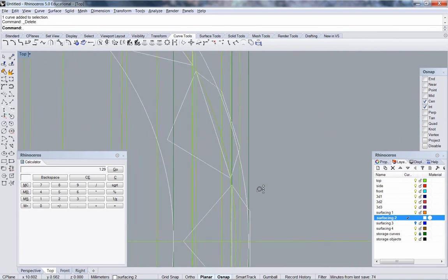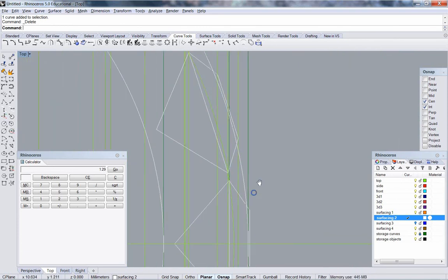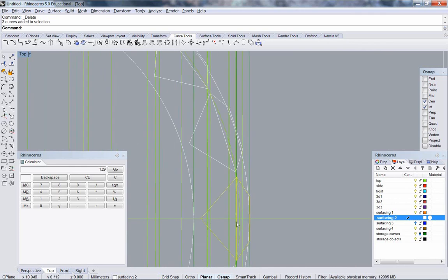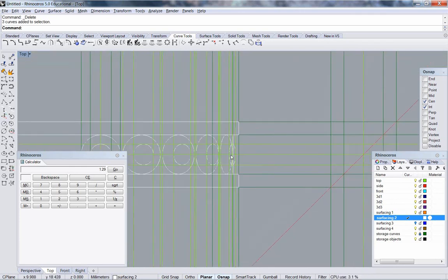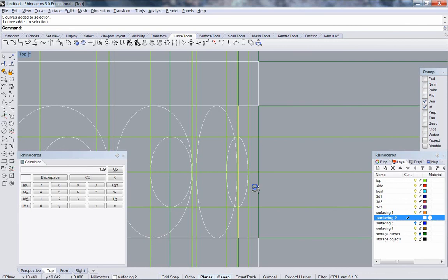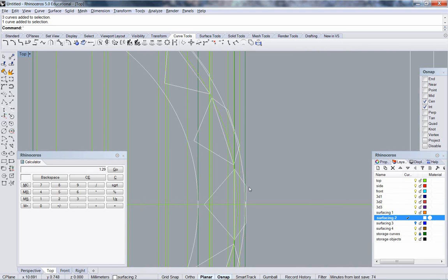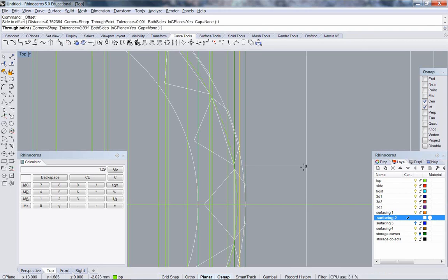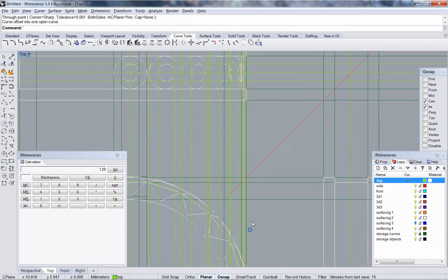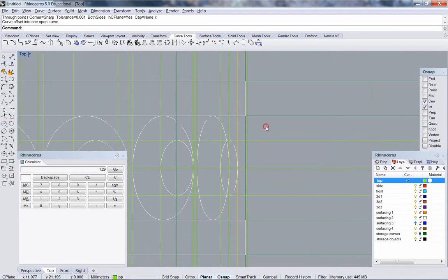Okay. My last stone. This line, the girdle line, is actually at the tray level. So we already have it. That tray line is the girdle. So all I need is the crown height, the table. So grab one of my vertical construction lines, offset, and grab the table. Then I can draw this stone with a polyline.